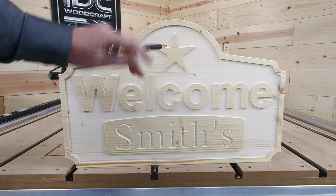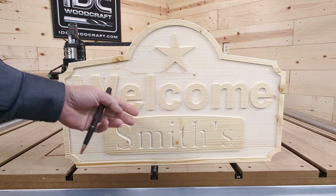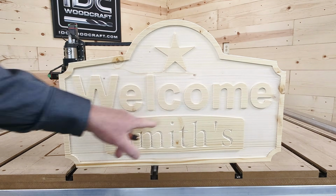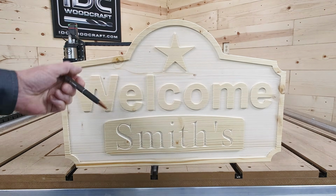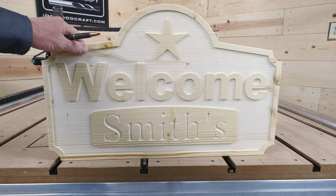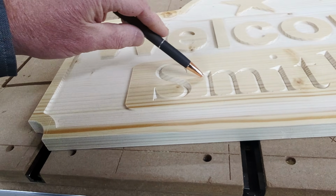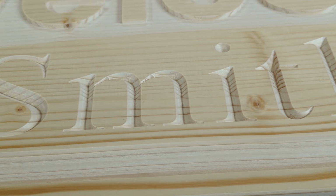The pocket cut is everything that gets recessed so that we get the star popping out, welcome popping out, and the big word Smiths popping out with that rectangle. And the third toolpath, the one I love the most, is V-carving. And that is this section right here where we will tilt this down and you can see that these are done in kind of a V-shaped wedge type of thing. That's where a V-bit comes in.